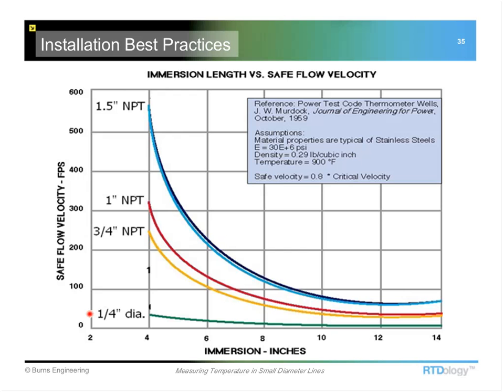So you really need to be aware of not only that stem conduction issue and getting in as much immersion length as you can, but we need to look at that flow rate to make sure that it's not going to be so high that it's going to cause other problems.